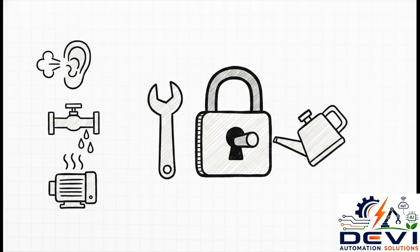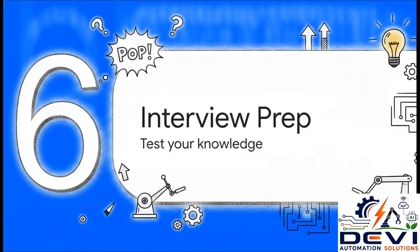But above everything else, safety first. You are dealing with highly pressurized air, hot fluids, high-voltage electricity, and machines that can move with bone-crushing force. Every single technician absolutely must know proper lockout and tagout procedures. You have to make sure every ounce of stored energy is released before you ever put your hands near an actuator. So the crucial point is understanding not just what these components are, but how you actually apply that knowledge out in the field.